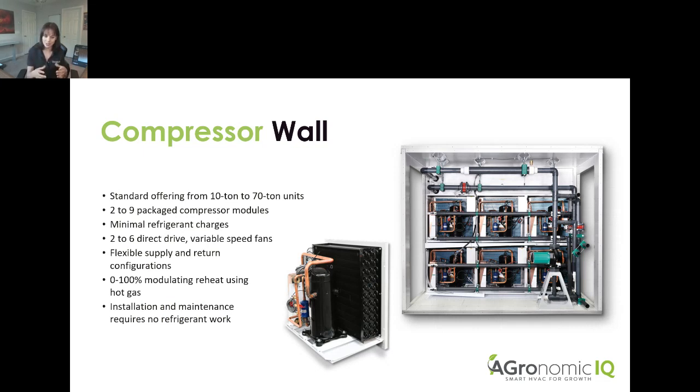module pods, we call them. So when you are on site or when installation is happening, all of your refrigerant is contained in these pods. And if you ever had a compressor go down, you could literally have somebody come out, pop out a pod, replace the next pod in about an hour and a half to 2 hours with 2 people, and you're back up and running.